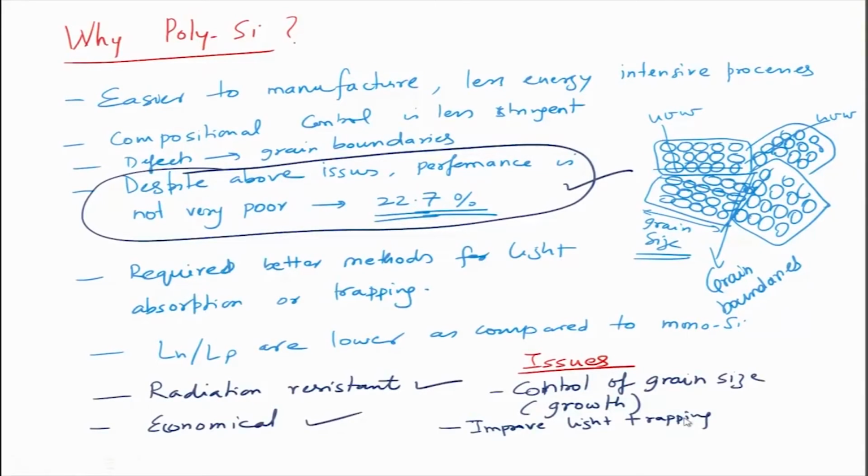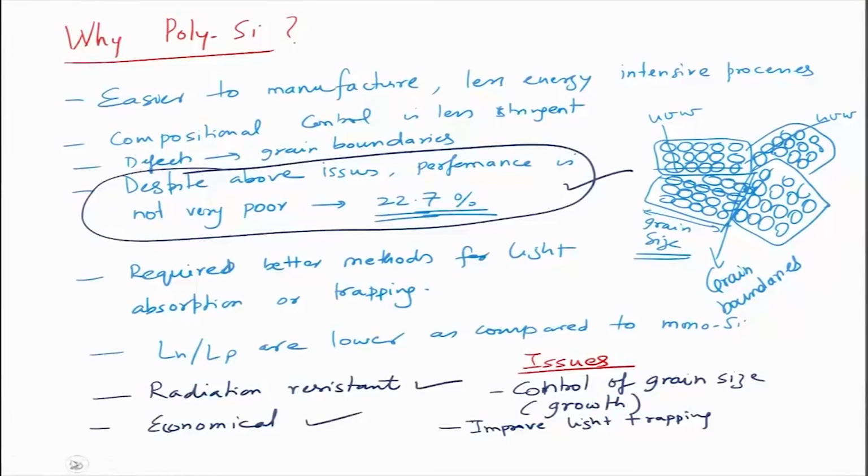Remember, in monocrystalline silicon, the top surface is all 100 plane, and when you texture it, you get facets of 111 planes. So, in single crystals it is easy. In polycrystalline you have multiple grains of multiple orientations. So, only etching will not work. Chemical etching doesn't work. You may also do some physical methods to improve the light texturing.